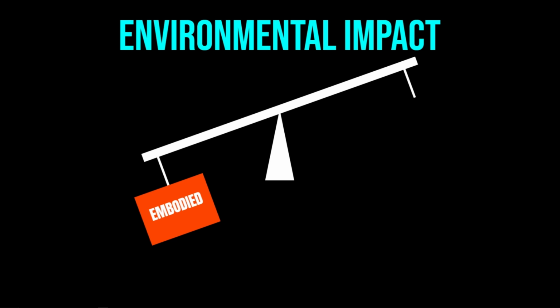Evaluating the environmental impact of insulation requires looking beyond the raw material. Mineral wool is made from abundant natural rock or recycled glass, but requires significant energy for the melting process. Polystyrenes are derived from crude oil, making them susceptible to price fluctuations in the petrochemical market. However, their lightweight nature reduces transport emissions. EPS is widely recyclable if collected without contamination, whereas XPS recycling is more complex due to the potential presence of older blowing agents.